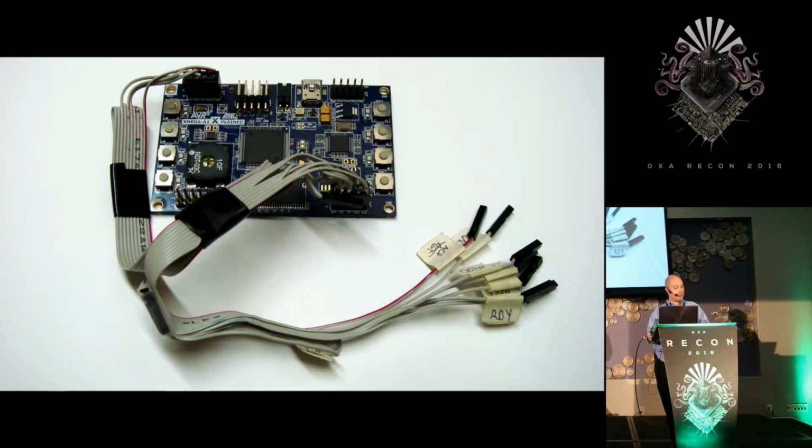There's selected programs that are decrypted. And so on the output of the ACP, we have the entire transport stream, but one of the programs has been decrypted. So my AVR32 logging interface had limited use, and later on I did some more thorough research, and at that point I pulled the ACP off and put it on a breakout board, and then I could control the serial clock, and it was much easier to use just an XMega.